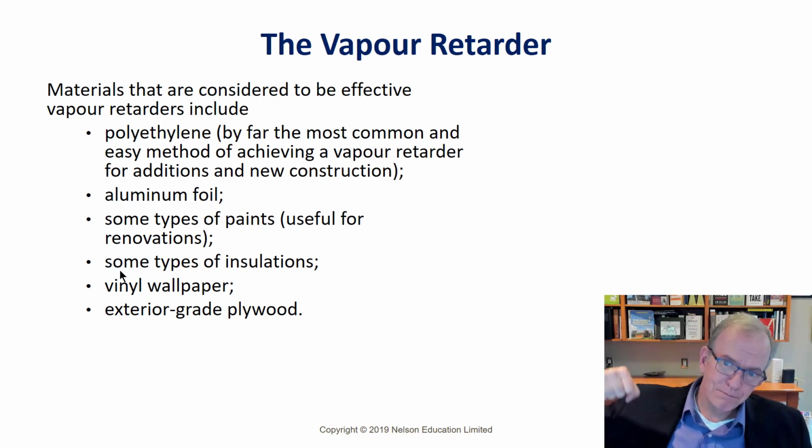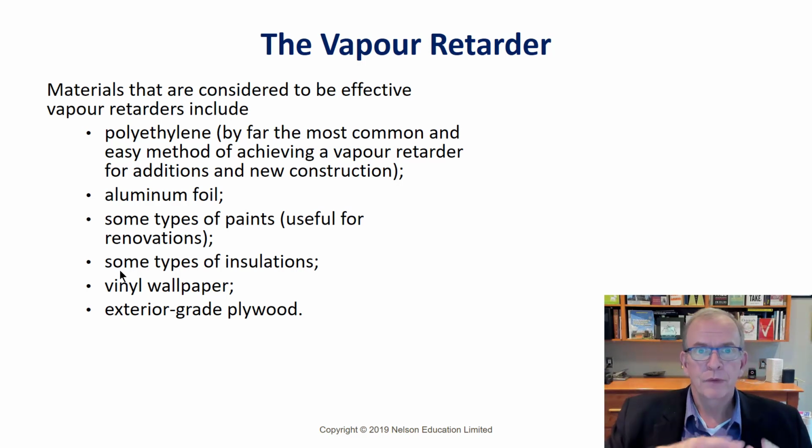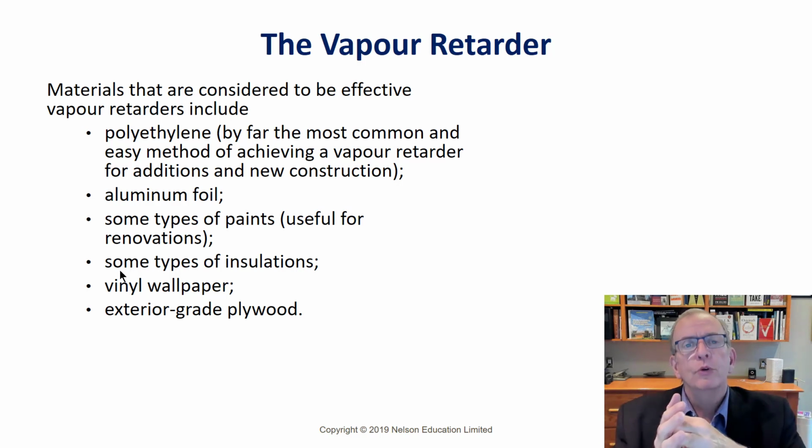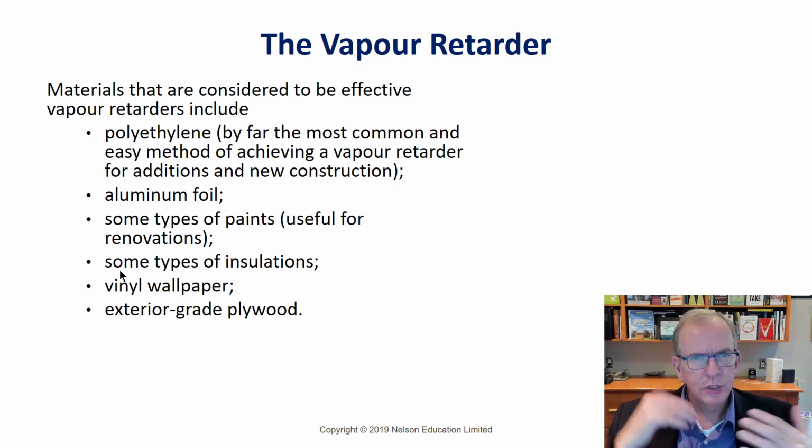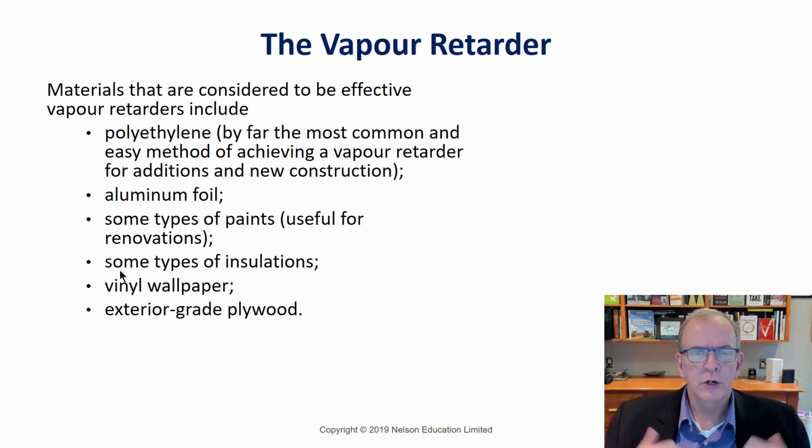There was a big pressure differential from the warm to the cooler side, which was air conditioned, and it diffused through the outside material right through to the back of the drywall, and then it condensed. So that was the vapor barrier coming from the other side. It's just what we were talking about, how air flows and moisture flows occur, and having a good basic understanding of why that would happen.